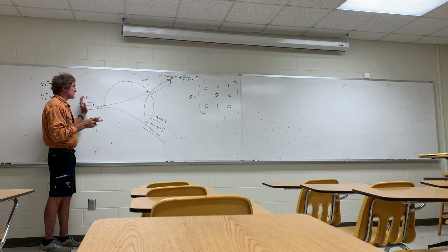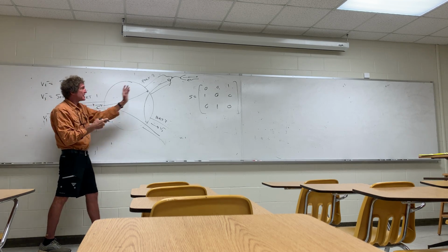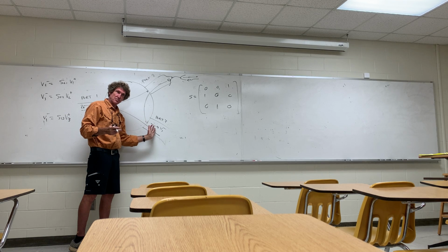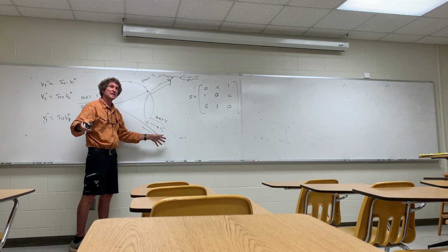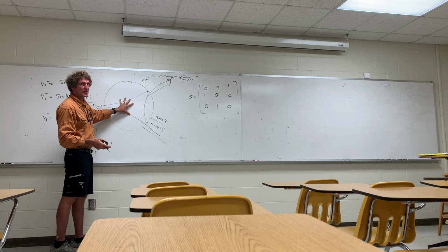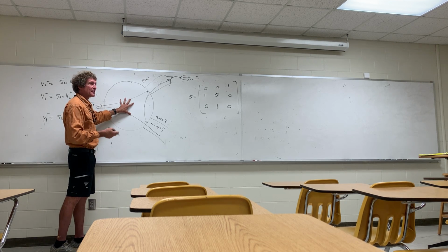I stop transmission and I start listening. As I'm listening, anything reflected back comes out this port. When it comes out this port, it goes and it's recorded, digitized, goes from A to D, and then stored. Then it does it again. But this circulator allows it to happen. A good question you're probably thinking is, how do you build that thing?